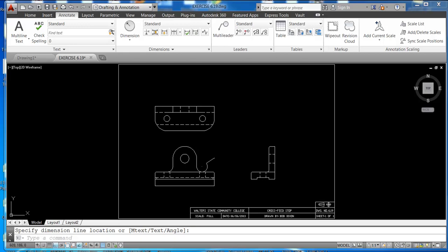You see here that I've got two dimensions on the front view of this drawing. One is below the drawing, the other is a radius off to the right hand side. You can see that with these two dimensions you can't see the numbers, you can't see the arrowheads on the leader lines. They're totally incorrect. A lot of times students, not knowing better, will try to change everything individually inside the properties drop down window. That's the wrong thing to do.